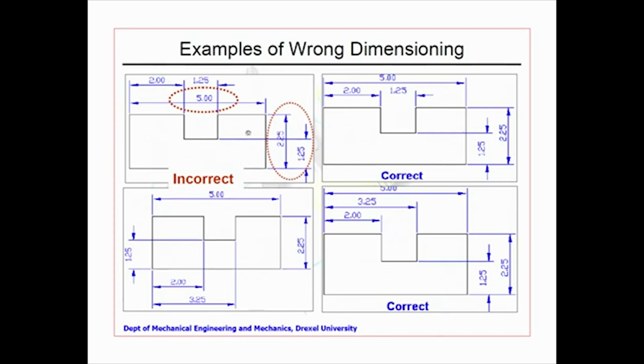So, if you look at a part like this, we do not know what it is. You see here there is 5 here, obviously this 5 refers to this. It is logical because somehow it leads to a wrong thing as if the 5 millimeter belongs to this. If you now place it on top of it, it is logically easier for us to read all these things. Two variants here: the groove width is given here and the starting point is given. In this case, from a datum line the things are shown here. So, both are correct, and logically if you place everything one after the other it will be easier to understand.